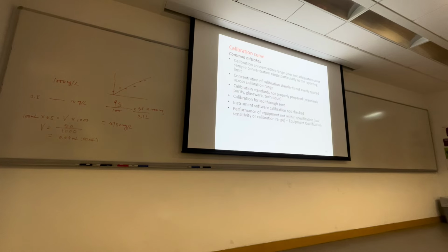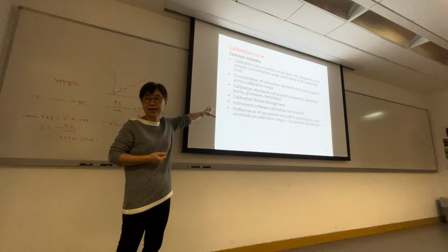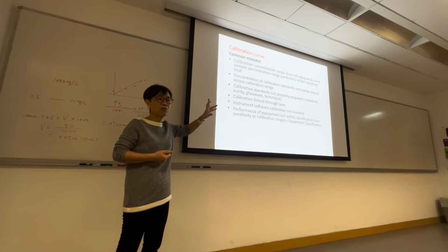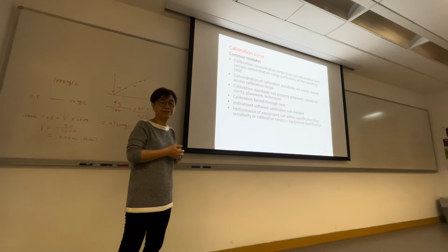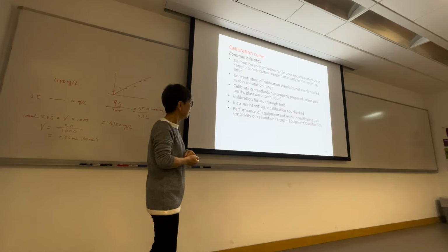Our instruments are very strong. Yes, their instruments are strong, but the application is different for different laboratories. So think about your intended use before setting any figures. Normally we just take linear and then use the 0 point also as one of the calibration standards.